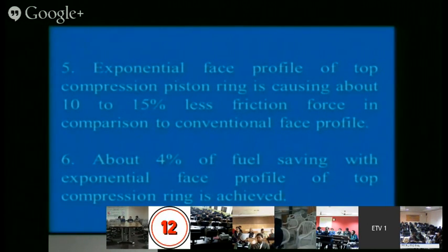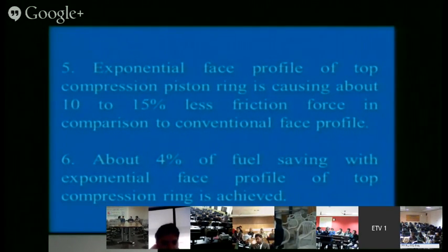So the next concept is that profile and surface texturing together will marry, and let us see what influence comes. Right now we are seeing that noise is reducing. Lubricant consumption we have also measured, and it is marginally reducing by 1.5%, but that data is not here right now. And fuel saving of 4 to 5% we are getting. Another point is that wear is reducing. Wear being less means clearances will increase at a slow rate. And if clearances at the contact increase at a slow rate, then it is good. Reliability is better, and the life of the contact will be better.